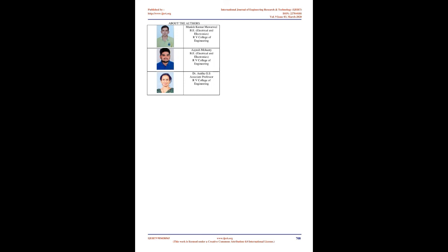Conclusion. ANFIS makes full use of fuzzy logic reasoning, which is simple, strong, robust, and accurate, along with neural networks. The ANFIS model was able to estimate with an average testing error of 0.092696. It can be used in real-time applications for estimating the SOC of the battery in case of missing data or unavailability of data. It's much simpler to implement and provides an accurate SOC value. Any battery data can be used to estimate the outcome irrespective of the specifications. It's really handy in situations where other methods give errors and are application specific.